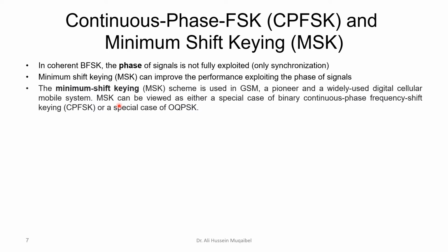MSK can be viewed as either a special case of binary continuous phase frequency shift keying, which we are doing now because we just finished frequency shift keying, or we can think of MSK as a special case of offset QPSK, offset quadrature phase shift keying. This is just to keep in your mind. For now, just keep this on the side and think about continuous phase frequency shift keying, which we just came from. We are exploiting the phase.